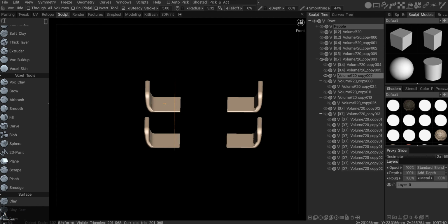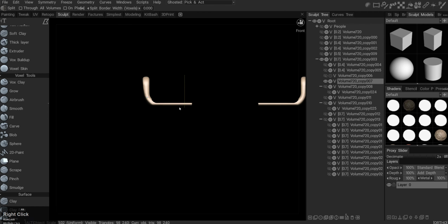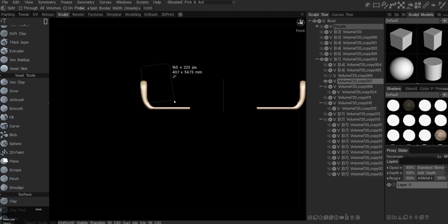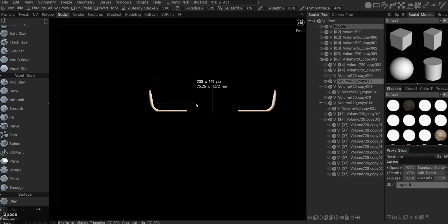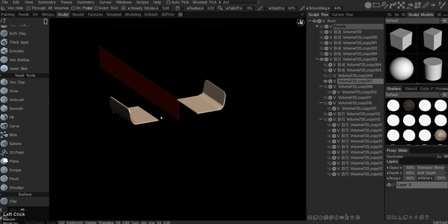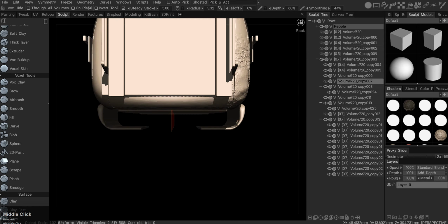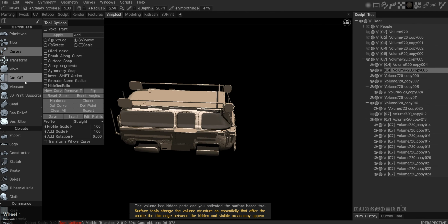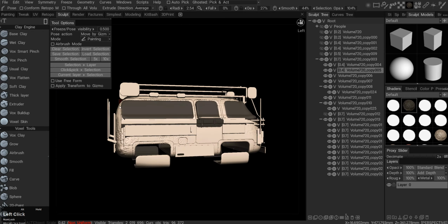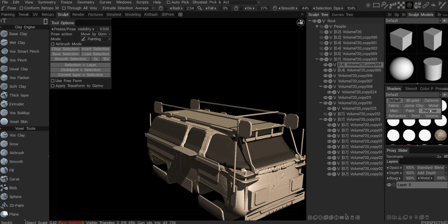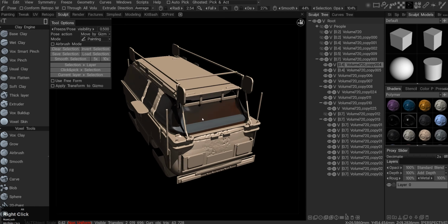Here I'm trying to thin out that shape, and it proved to be a little bit more difficult than I thought. I'm just trying to make it thinner. It's one of the common design mistakes when people make the shapes too thick. In real life, that metallic part would probably be 5 millimeters thick at most, probably even less, probably 3 millimeters thick. Actually, 5 millimeters is quite thick. I would go for 3 millimeters thickness for the metallic part.